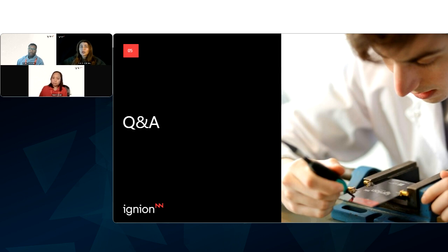Then when you do your prototyping, like when I worked with some consumer electronics, and I had such a device that's supposed to go on concrete or on the metal or even on the ground, that's what I did in the lab. I put some bucket with the ground and put the antenna or device there and checked it with my VNA or in the anechoic chamber. Or if I needed a metal pole, I put the device on a metal pole, and that's how I tune it, and that's how I test it, because that's how it will work.